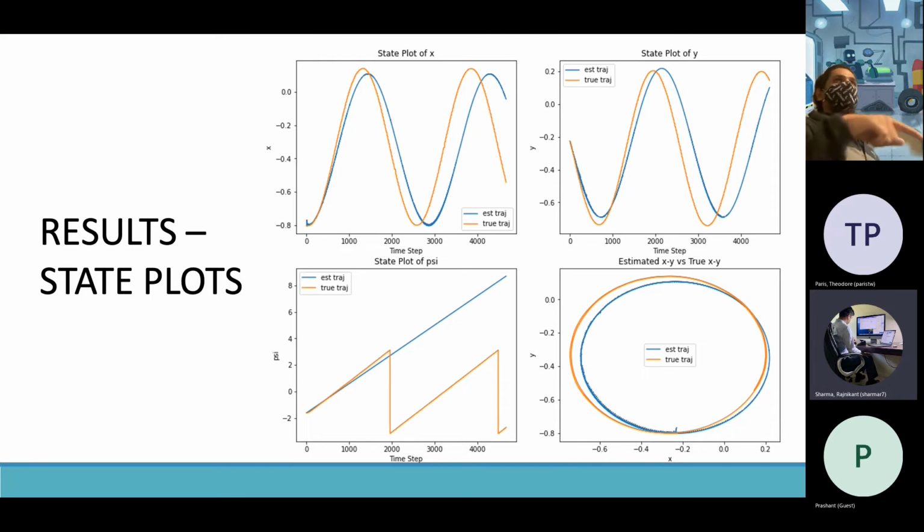But in our state space equation, we included the landmarks, and because our covariance matrix changes, the landmarks... Still, you're saying x dot is 0. So the prediction model always says this landmark is not moving. You know the true position at the starting t equals 0. So saying that you're navigating in an unknown environment, and all those conditions are kind of... So the right way to do that would be to take the relative distance between the landmark and the initialization process.